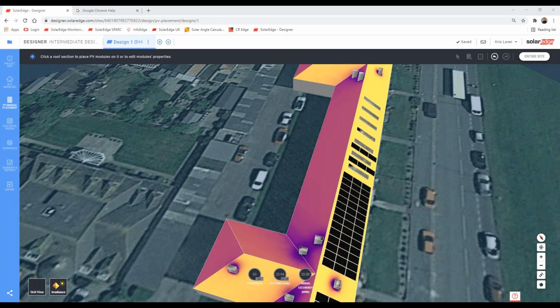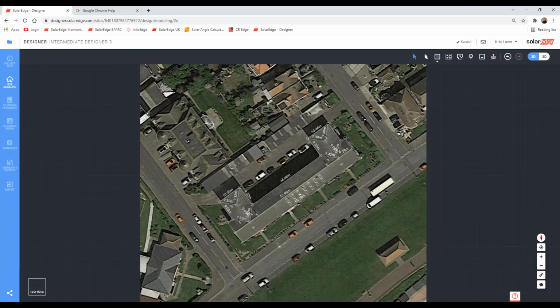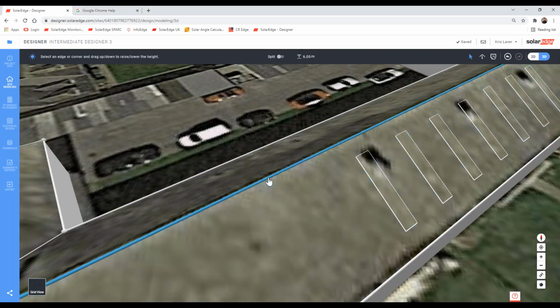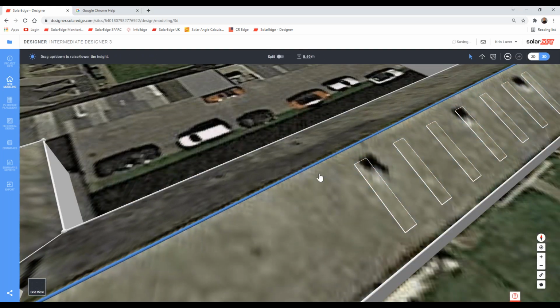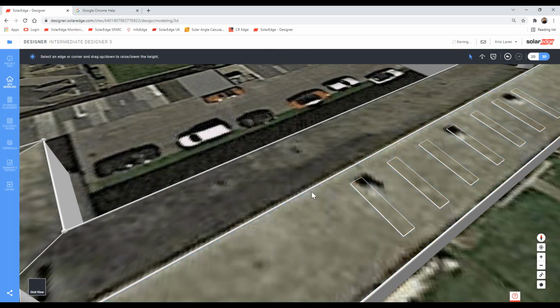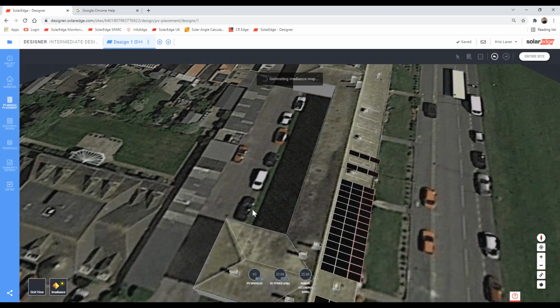So for example, I think on this one you've got 30 degrees. If the roof pitch was down at say 10 degrees, then potentially the generation would be much higher on say that north facing roof. So Chris is just obviously reading my mind straight away. Bring that facet down. So now we're at say 10-degree pitch, and this is obviously quite important for commercial projects.